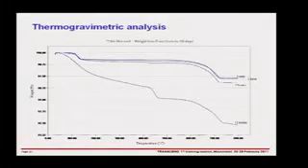Okay? In many, many studies going back to Powers, people talk about chemically combined water and physically combined water. And they talk about the chemically bound water as being material that's present at 105 degrees. 105 degrees is huge for these hydrates. You've already lost nearly half the water in your CSH by 105 degrees. So this is very, very important in reading old papers, particularly where they talk about things like chemically combined water or bound water, because you've already lost a lot of water that's in your hydrates.